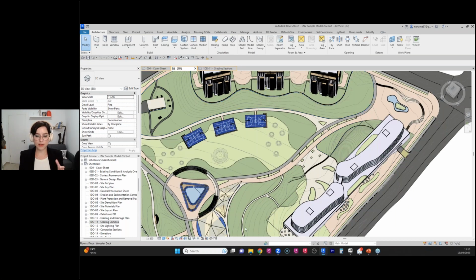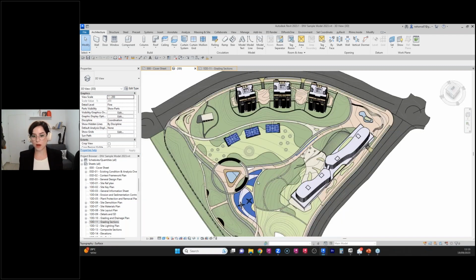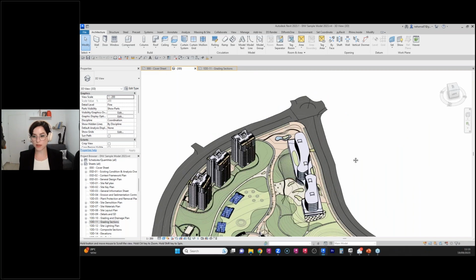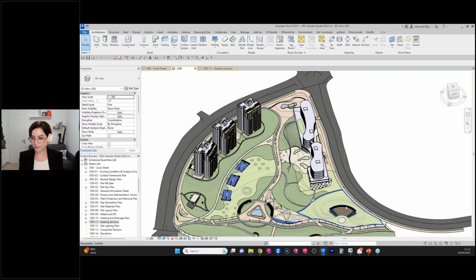So having said these three principles of not one big surface, using primary and secondary surfaces, and then starting from flat and slowly assigning the grading and elevation, now let's jump into environment tools and take a look at how our topography tools can give you the flexibility to do that.